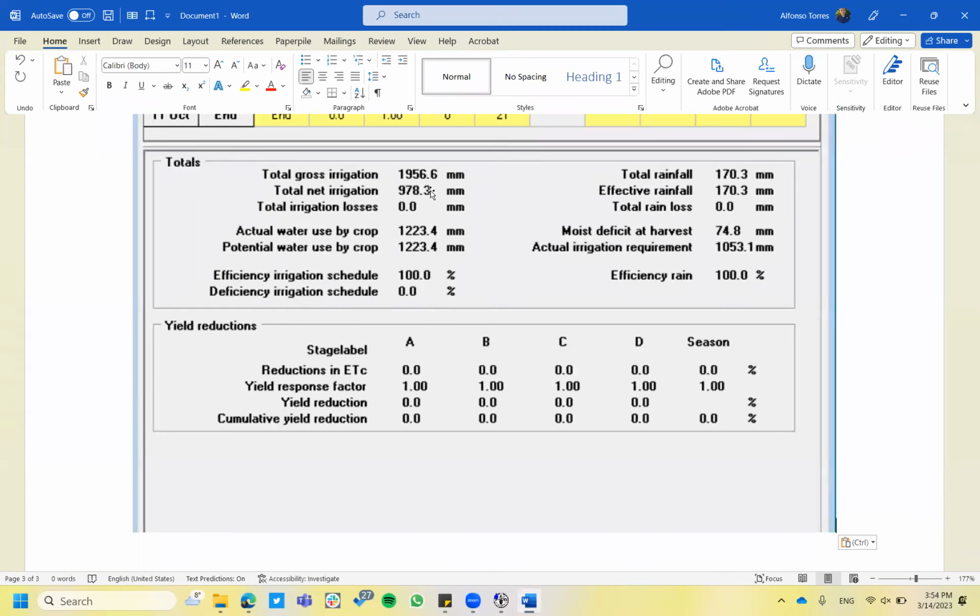We enter the rainfall information. We check those crop coefficients that FAO is giving us, because typically there are local studies that say, don't use FAO, use these crop coefficients, okay? You enter that and you can simulate the scenarios that compare current conditions, technology 1, technology 2.